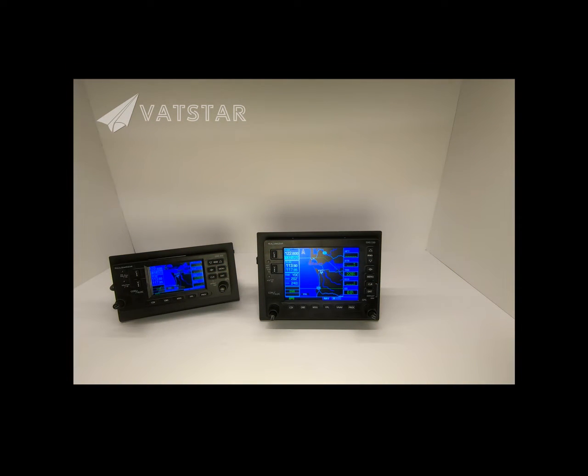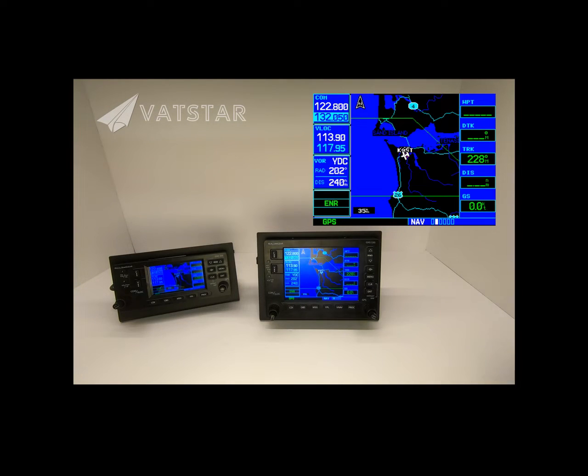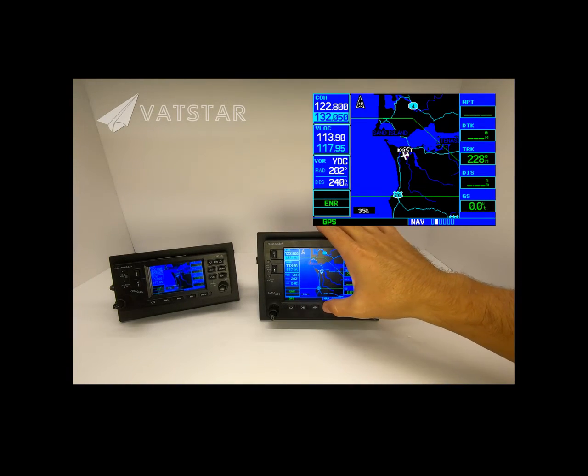So now you want to set up a flight plan, and we are sitting at Astoria Airport, and that's Kilo Alpha Sierra Tango. We're going to be flying to Kilo Tango Tango Delta, and that's in Portland, Oregon, right? It's a very short route and a very easy flight plan to input, but you guys can have an idea on how to do so, right? So the first thing you're gonna do is hit the FPL button, the flight plan button.